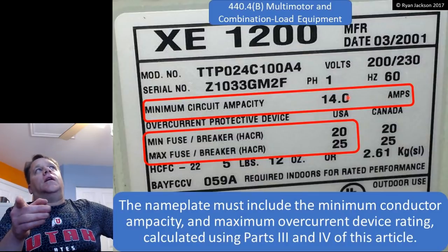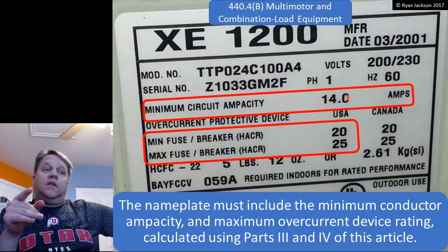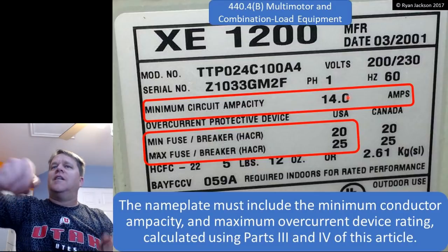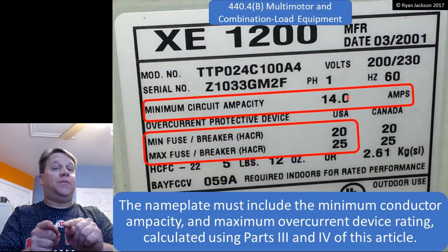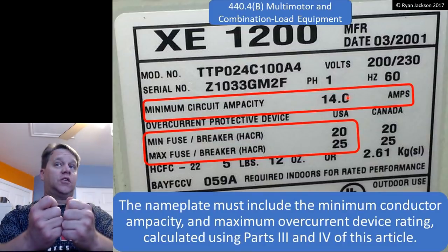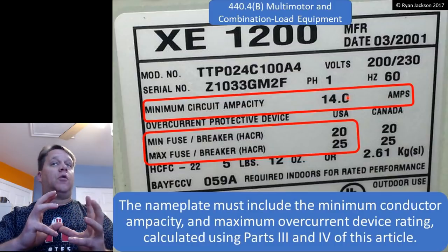Have you ever had to open up the cabinets under your sink, reach under there, and push the button on your disposal because food or something got caught in the blades? That is built-in overload protection. That motor stopped spinning because food got caught in it, and it was trying too hard, and it was starting to pull more current because it's basically like a locked rotor condition.